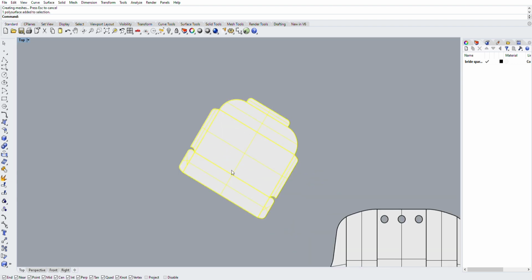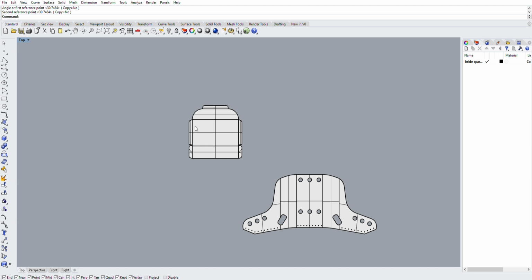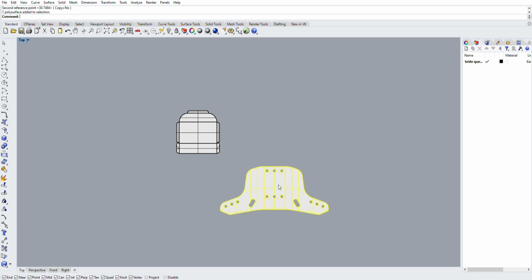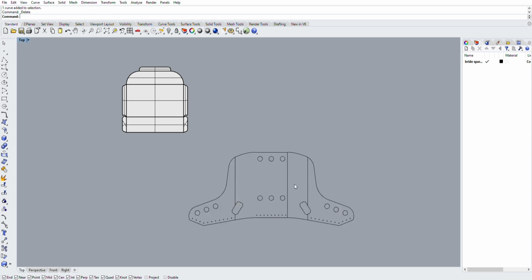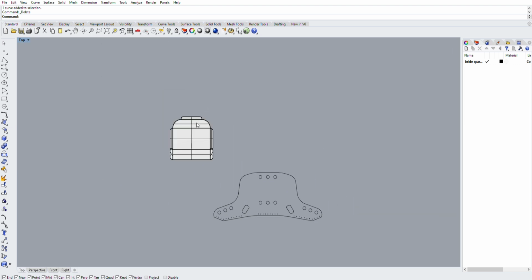And then I redid the surface unroll, or the unroll surface command here. Now, if we go into our curve edits, there's a command in curve edits that is duplicate edges from surfaces, and it'll say select your edges, and we can actually select all of the edges here, hit enter. And then we can go back in and delete our surface and go back in and delete our lines. These lines would have been the beginning and end of our roll, essentially.